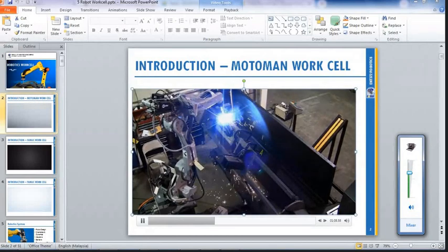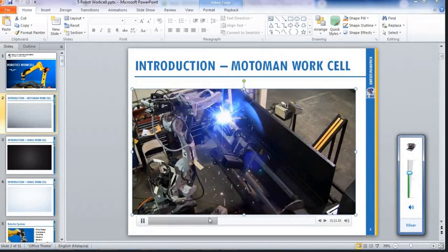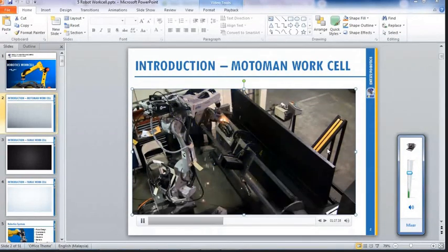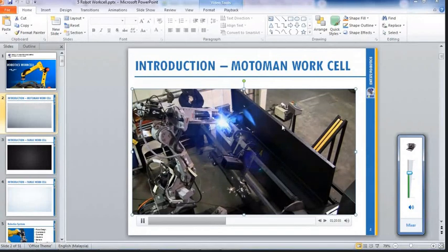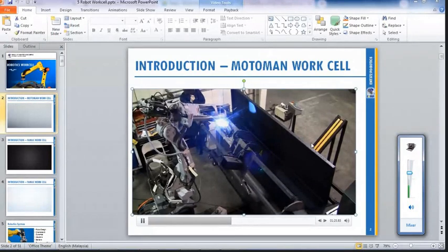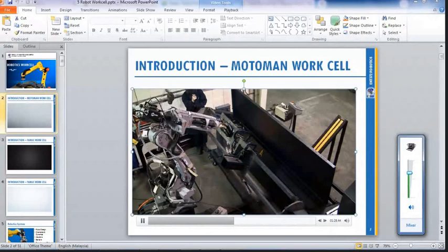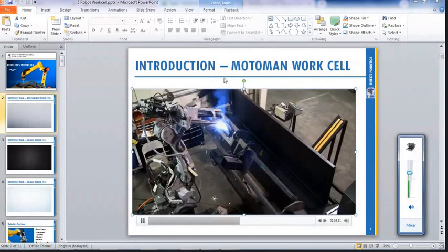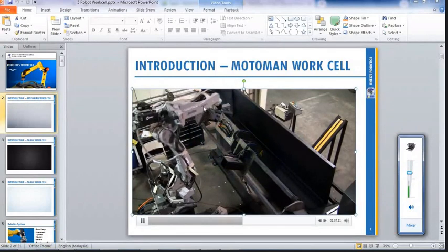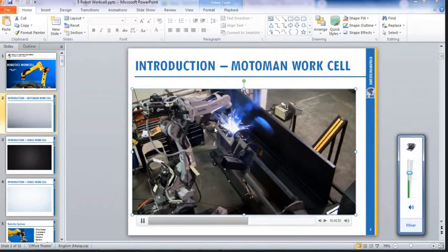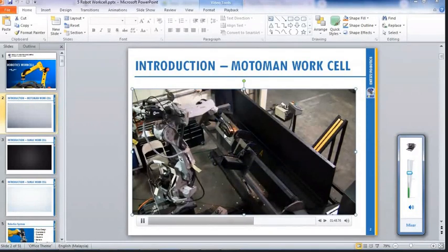Normally in a robot work cell, they have a cage surrounding the robot for safety. The cage might be mechanical, something like a grill, or maybe you have a sensor, like a laser or infrared sensor. In this case, it's a little bit dangerous, because the operator can enter during the assembly process. But in this case, maybe the operator is required to confirm whether the welding is correct or not. So the operator needs to enter the process.